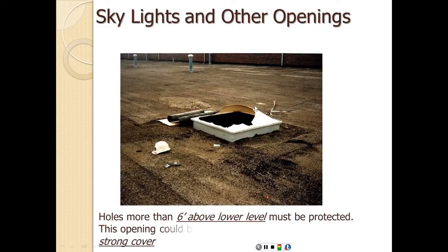Skylights and other openings in roofs, again, obviously that's a falling hazard. So holes more than 6 feet above a lower level must be protected. This opening could be made safe by using a guardrail or a stronger cover to protect from falling.